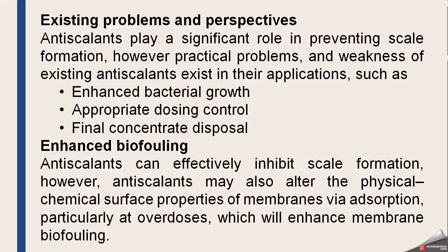Antiscalant can effectively inhibit scale formation. However, antiscalants may alter the physical chemical surface properties of the membrane via adsorption. So if they are overdosed, by this phenomenon, this will enhance the biofouling of the membrane.